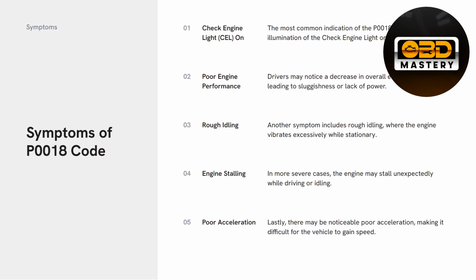Now, what exactly are the symptoms? So, you're going to have a check engine light, poor engine performance, rough idling, engine stalling, and poor acceleration. If you're blipping the accelerator pedal and you're getting very little to no power, and it feels a bit sluggish, you're not going to have the power that you once had.